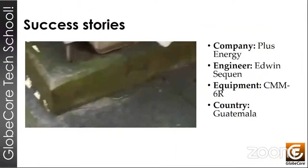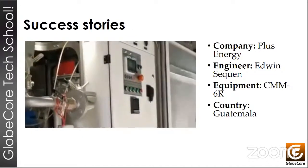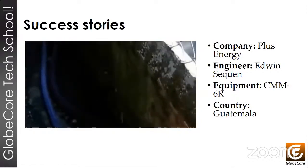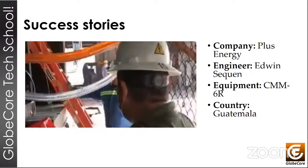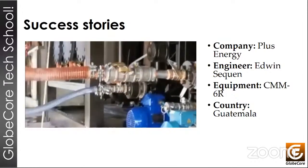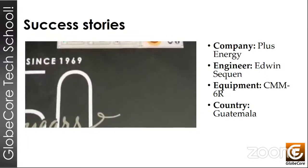Next slide, please. Here we have another example of transformer oil regeneration. This was in Guatemala, and we have a brief video to demonstrate it. You'll see that in this process, the oil goes into a vacuum purification machine, a vacuum dehydration unit, a degassing unit. In just a minute, you'll see how that process works. So in the vacuum dehydration machine, what happens is that oil is subjected to heat and vacuum that extracts any gases and any moisture from the oil, right? So in a minute, you can see the control panel of the machine.